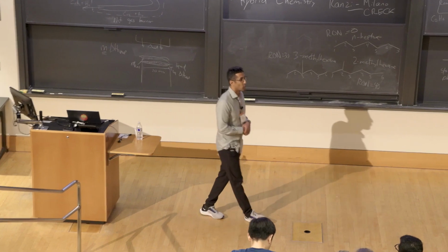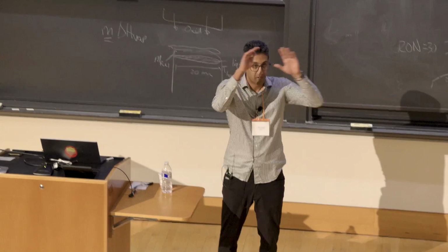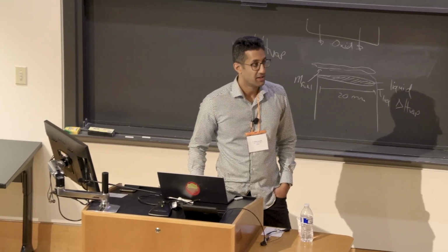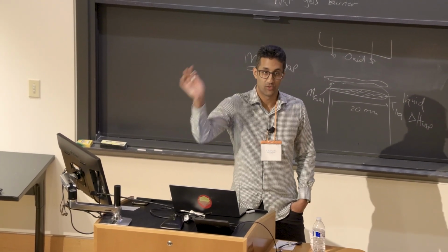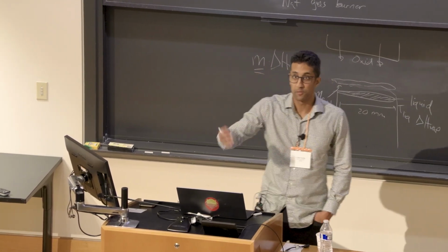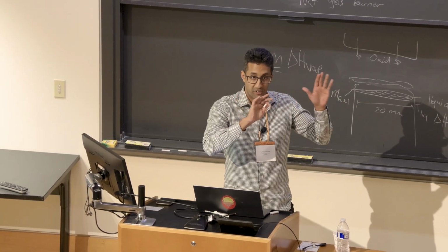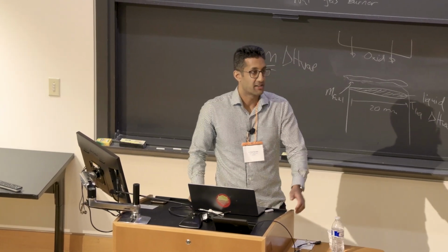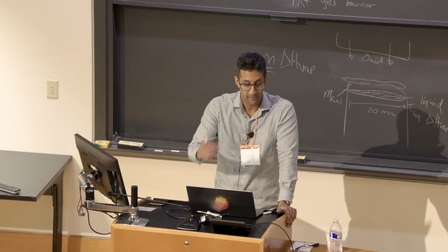And we asked ourselves, why does it work? Well, it works because he has constrained the reaction model against experiments which predict the intermediate pool of species. And if you have that right, and then you put that into a model to predict something like ignition and flame speed or extinction, it works because you got the concentrations of all those intermediates correct from the fuel, and then you have a good model to predict how these intermediates break down and form things like H, OH, CH3, which lead to the combustion phenomena that are manifested.